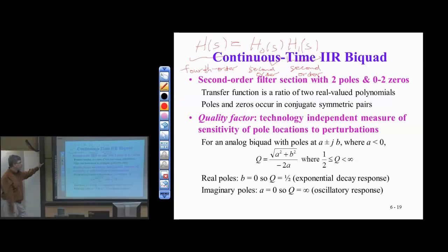As it gets more interesting, for a 10th order filter, there are a few more combinations. It's factorial. And then I also haven't told you how to choose the zeros yet, but we'll do that. So there's also another permutation in how you match the zeros with the poles. So you try all possible combinations of that, by simulation, until you're happy with one of the choices. But barring simulation, there's a nice rule of thumb using quality factors to decide what order to use.